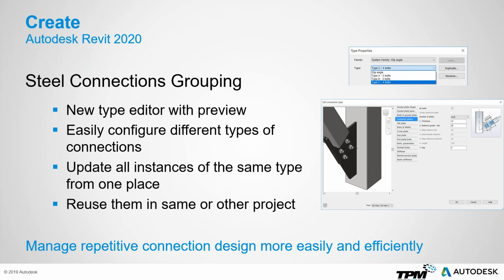Now, for those of you working with Revit, these family types are where we're going to be changing our properties now. In the past, the properties of a steel connector were instance-based. That was convenient, but it also made it almost impossible to propagate or use that same type of steel connector at multiple locations. So they've moved the ability to edit those parameters over into the type properties. And that's what we're seeing here with the edit type parameters. You configure how you want those connectors and those elements to be within the steel connection. You can see a little screenshot there. And once that's been developed, we can then propagate those connections over to other members, and we'll be showing this live in a little bit with the demo as well.